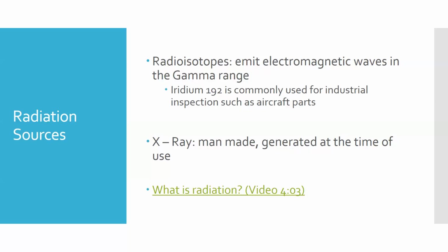Last week we left off looking at what radiography is, what kind of inspections we do, and some of the key features. The biggest things are that it allows us to see both surface and subsurface flaws. That's a big advantage. The big disadvantage is we're dealing with hazardous radiation, so there are a lot of safety precautions we have to take, and training and tracking that has to take place in order to do it safely and legally. The Nuclear Regulatory Commission requires you to file permitting, and they do inspections and all that kind of thing that go along with any kind of radiographic sources.